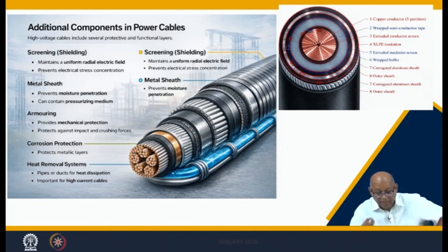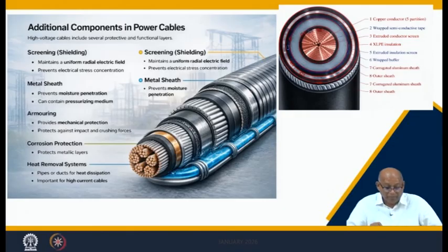As I said initially, the first and foremost thing is electricity. Actually, safety. Safety cannot be compromised at any cost. Then it has to carry electricity. Then it has to be mechanically strong. It should be resistant to chemicals, it should be resistant to fire. That means there are cable materials which, if there is fire, will automatically extinguish. So these are all designed as per very strict standards, strict guidelines. If you are going to install cables in a mine, you have to follow the strict worldwide standards.